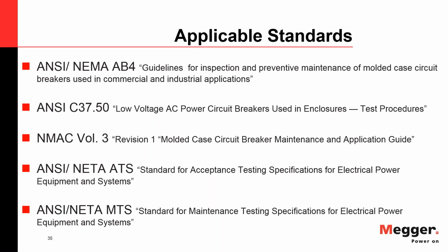Well, now one could argue that on the long time test it doesn't really matter because there are so many cycles that this little asymmetry, if there is one in the beginning, doesn't matter. Technically that is true, but for any test you should always eliminate the DC component, specifically for the instantaneous test, because it will be at least an inconclusive or even invalid test.